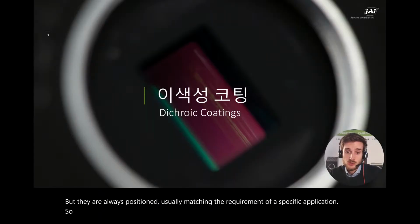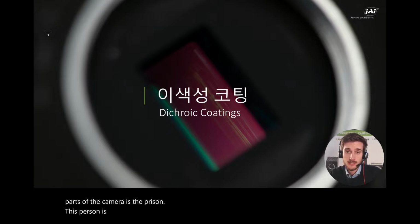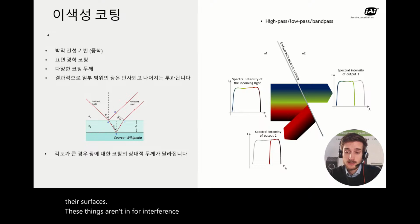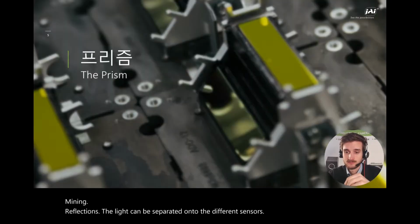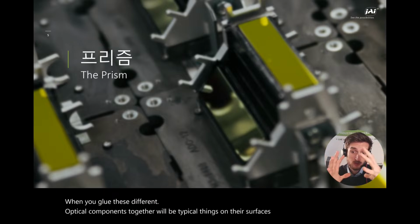So how is JAI building these multispectral cameras? One of the most important parts of the camera is the prism. And this prism consists of multiple optical elements, all these elements with dichroic coatings on their surfaces. These dichroic coatings are thin film interference-based. And these thin film interference-based coatings are evaporated on the surfaces of the different glass materials, which are then glued together. And combining dichroic coatings with total internal reflections, the light can be separated onto the different sensors. When you glue these different optical components together, all with dichroic coatings on their surfaces, the complete optical assembly will be called the prism.